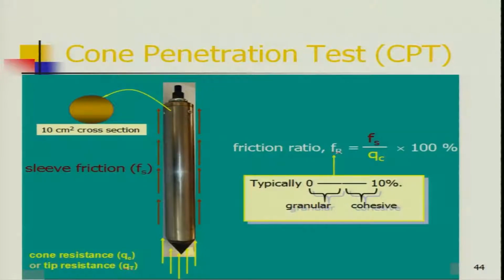So, we have finished standard penetration test, plate load test, DCPT. Now, cone penetration test. Cone penetration test measures tip resistance as well as frictional resistance. Generally, it is used for design of pile foundations. Cone penetration test is called CPT.